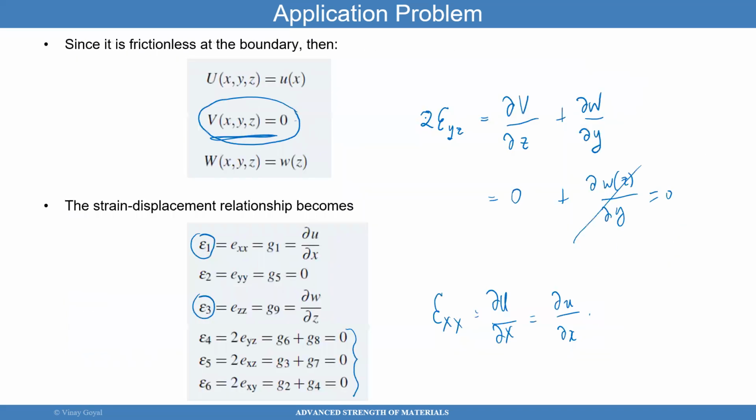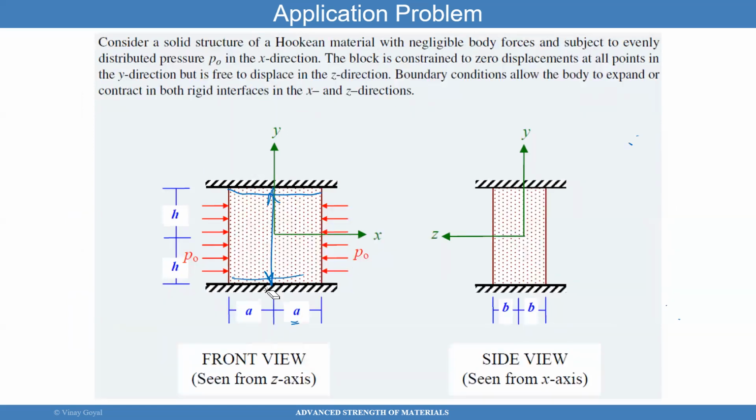Okay, let me say why. If I'm applying a load uniformly, laterally to this block, I'm going to say that very likely the center line will stay untouched. It's not going to move left or right. So I'm going to say that the deflection U at that location is 0. And that's true for every point here, actually. So I can make this into Y.